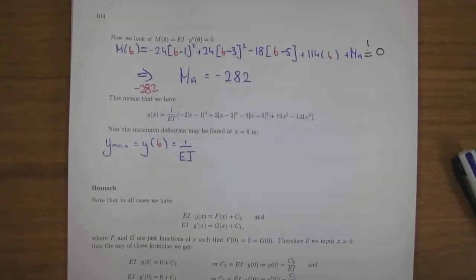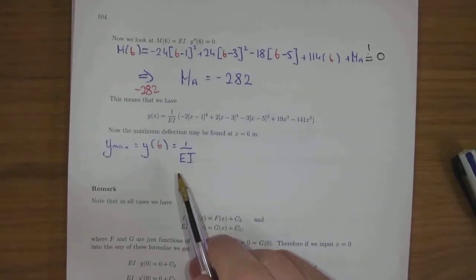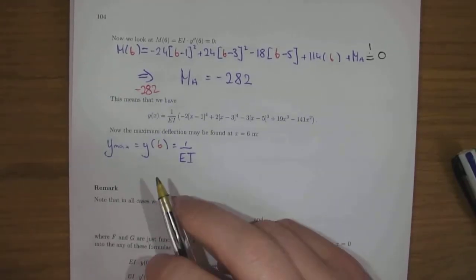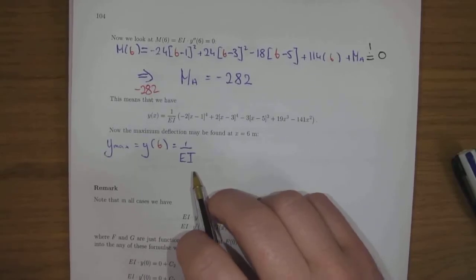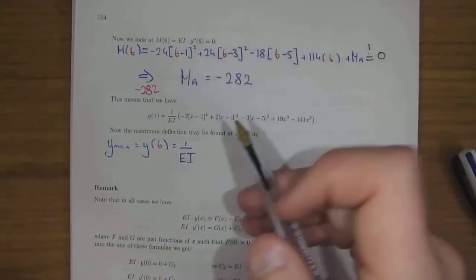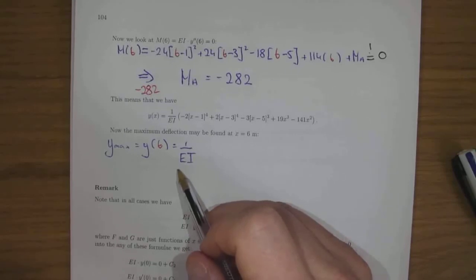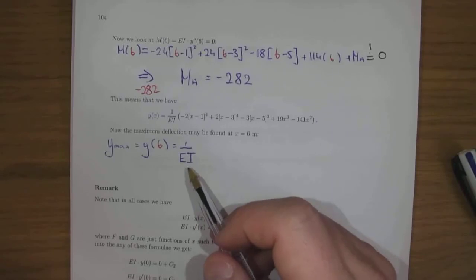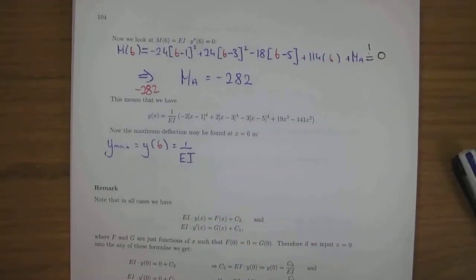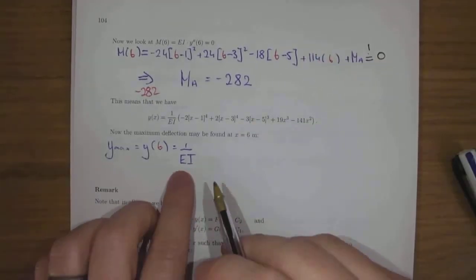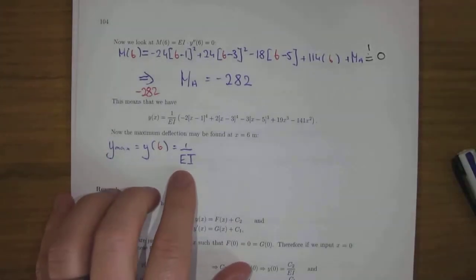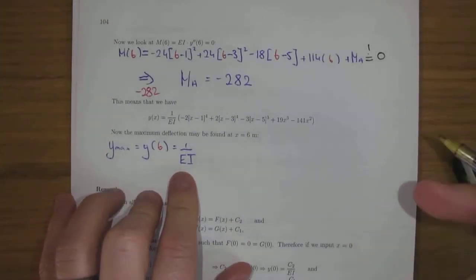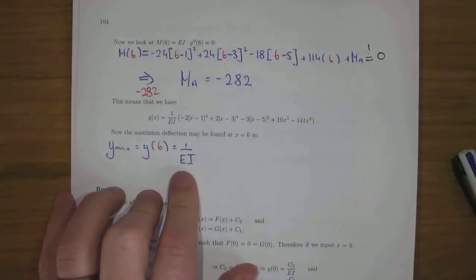Remember, if you're a bit confused by the EI, by keeping the E and the I not as actual numbers, if you change the material of the beam, that's changing the E, or change the cross section, that's changing the I, the math still applies. So the E is the Young's modulus. The stiffer the material in that sense, the larger E is, and the I is related to the second moment of area, so changing the cross section will change that. And you can make the deflections bigger and smaller by stiffer beams in terms of material, stiffer beams in terms of cross section.